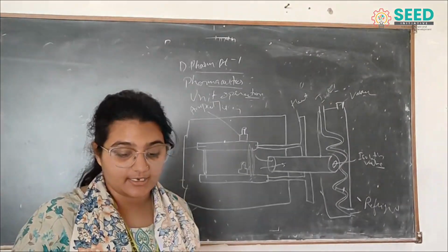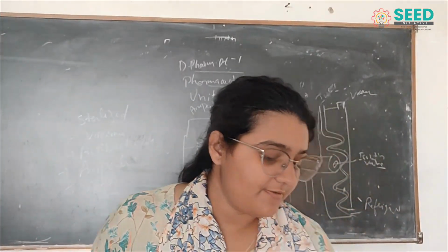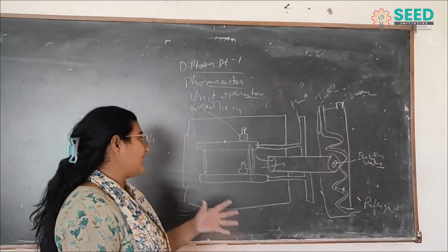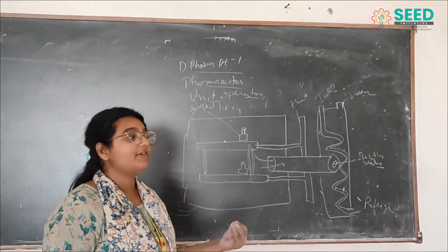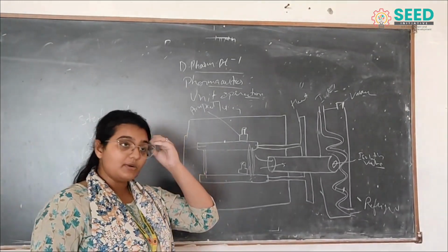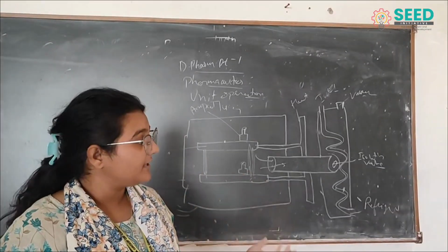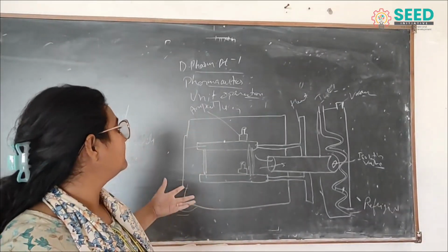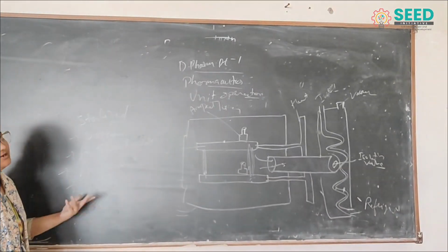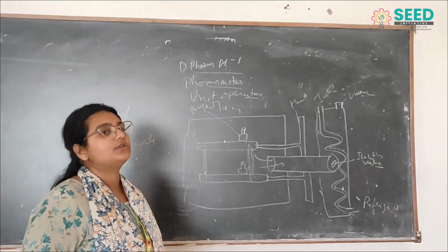Application: it can be used for different applications. Now we talk about the disadvantages. The running cost is very high and it's a very time consuming process, because normal tray dryers, spray dryers and fluidized bed dryers dry materials in an interval of 5 to 7 hours, but this can take up to 26 hours, even 1 or 2 days, depending on the solvent.